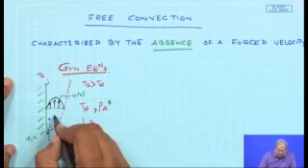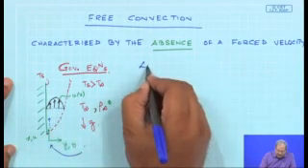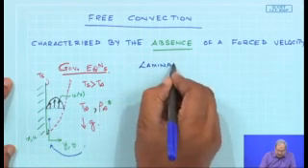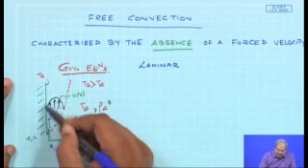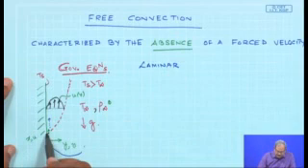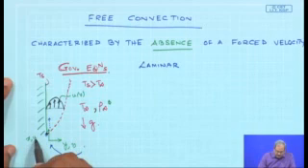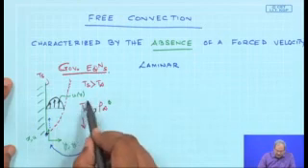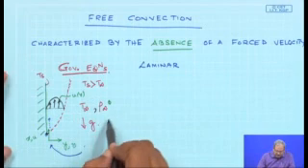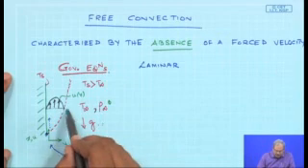Let's assume that the density difference imposed flow inside the boundary layer is laminar. However, it is also possible that we will have turbulence at some point at a larger value of x. So this is x equal to 0, y equal to 0. That's the origin that we have, and the velocity in the x direction is u. The velocity in the y direction is v. And we understand that the flow outside of this thin layer is essentially stationary. So both u and v will be 0 from this point onwards.